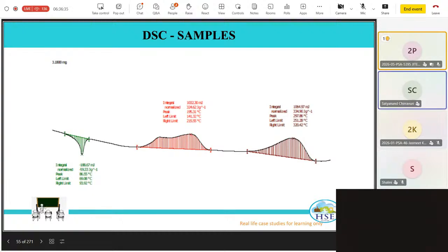Once a normal reaction happens, as in any typical chemistry, there is always going to be a small incremental reaction rate, and that will result in a slight temperature rise slowly. TMR 24 means at that particular temperature, you leave the reaction by closing everything and not allowing heat to be removed or heat to be absorbed.